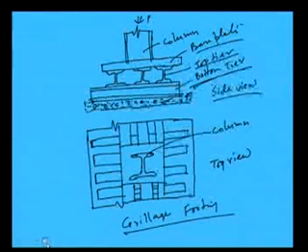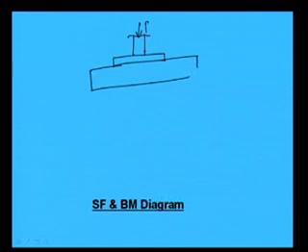Now before going to analyze, let me show the shear force diagram and bending moment diagram of the footing, how it is coming. Suppose load P is coming, resting on the base plate, and then it is going up to the beam. So when we are going to design this beam, we have to know how much load is coming on this beam and where the maximum bending moment and shear force is going to occur.